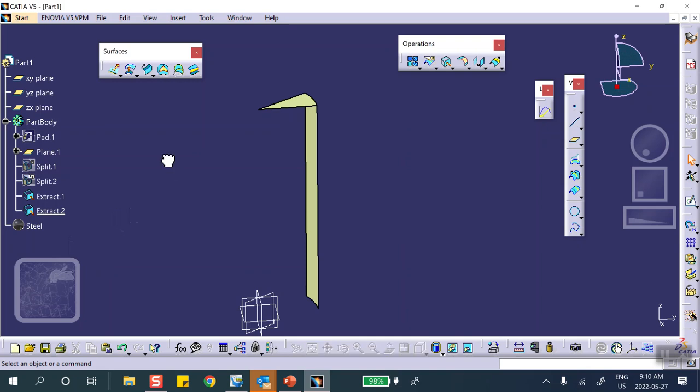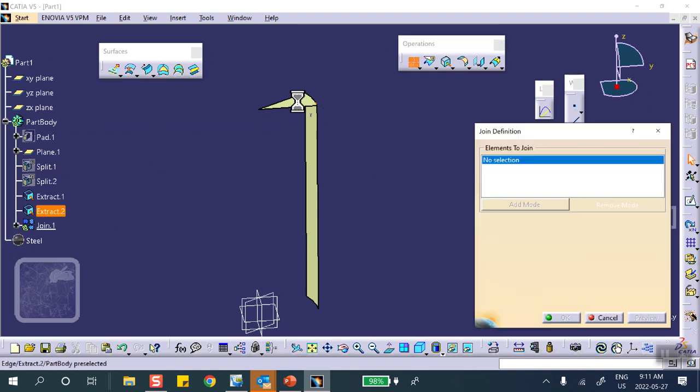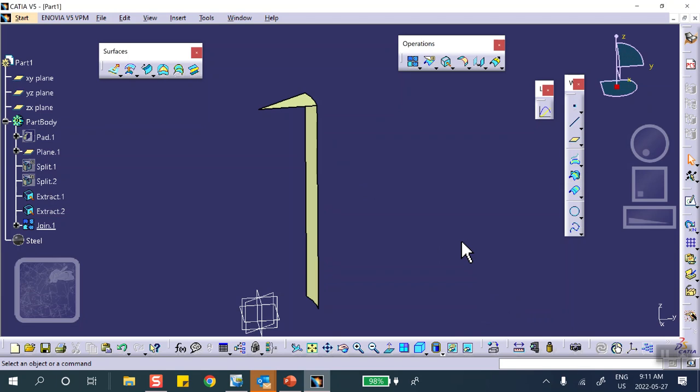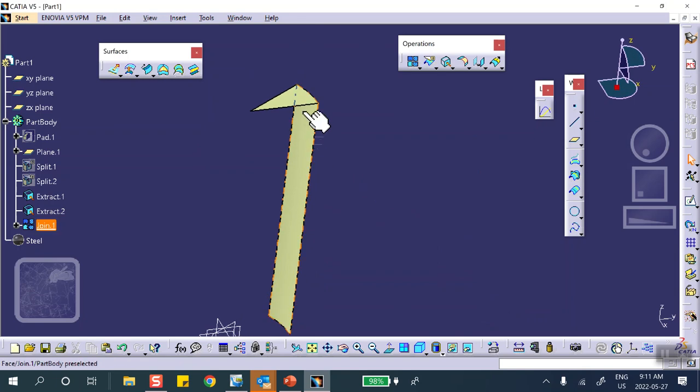Okay. Now, because I don't want this issue of connections and things like that, why don't I join them? Join this to that, so that we don't have that issue of seams and things like that. Now, because later on I want to apply a certain restraint on these two edges, there is no problem because these two edges happen to sit in the YZ plane. On the other guy, the other two edges are not in the YZ or XZ or XY plane. So I have to create a coordinate system for that. And let me remind you how we do it.